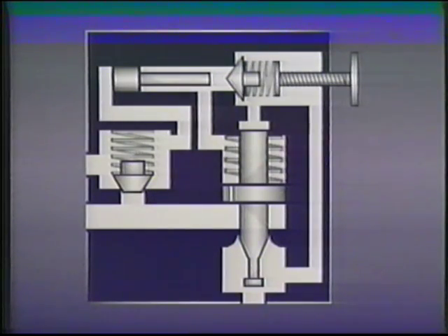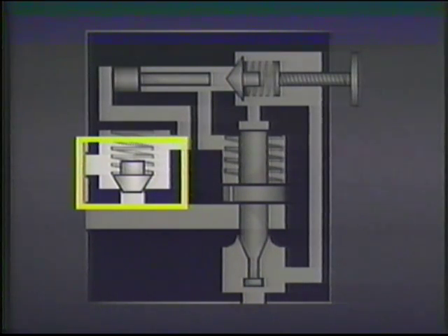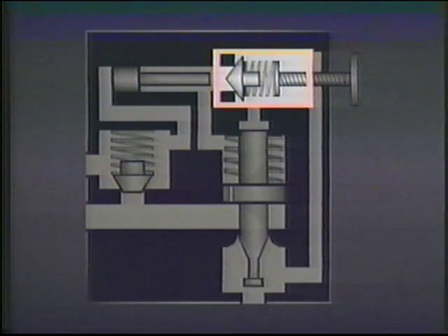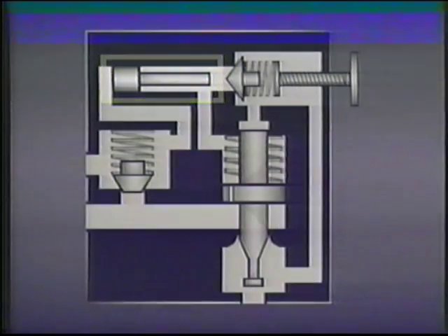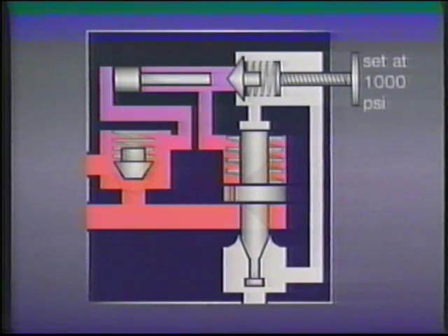This special relief valve includes a main valve spool, a check valve, a pilot line, a spring-biased pilot valve dart, and a differential piston. They work together to enable the valve to open and close as pressure rises and falls. Here's how it works. When the accumulator is being filled, flow from the pump, shown in red, goes past the check valve and into the accumulator,